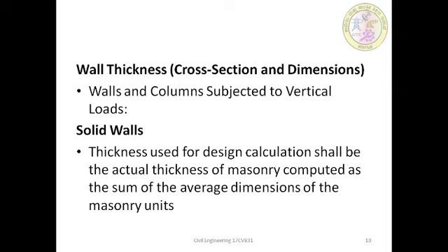In masonry with raked joints, the thickness shall be reduced by the depth of the raking of the joint for the plastering or pointing. Now, brickwork is generally finished by either pointing or plastering, with that in view it is necessary to rake the joint while the mortar is green.